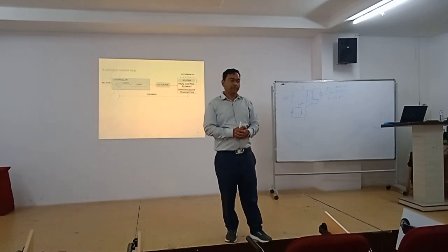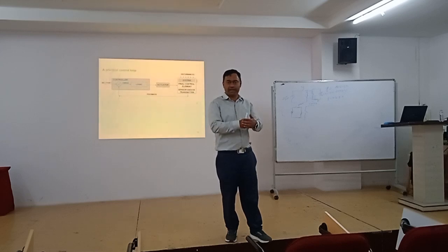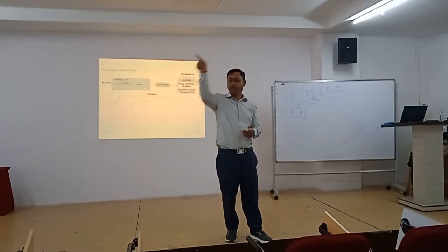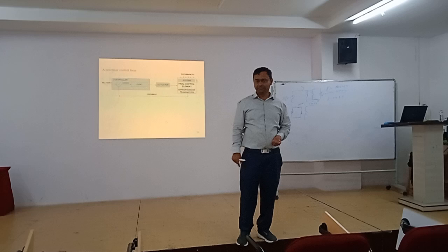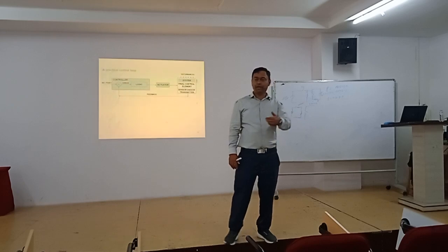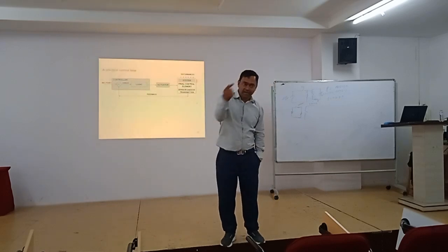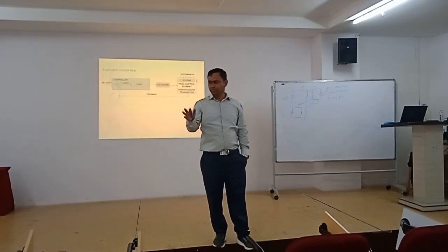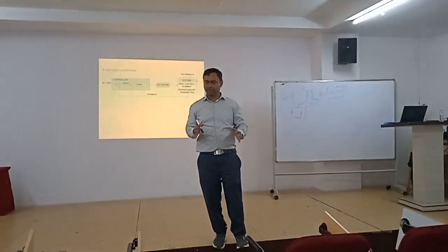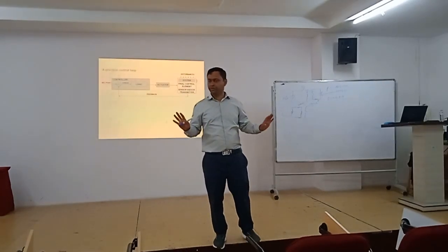So we have the induction motor which is working with the air blower, which is blowing the air through the pipe. We want to control the flow. So what do we need first? The blower is there because it's a part of the system, right? First we need to have a flow sensor. As a flow sensor, we have gone for the orifice. Maybe somebody might be studying the working of the orifice. The orifice works with differential pressure.